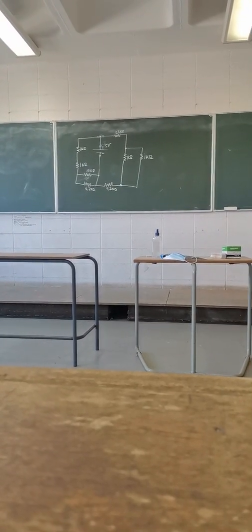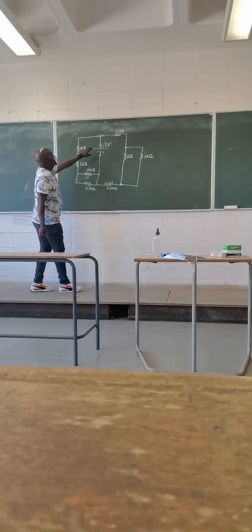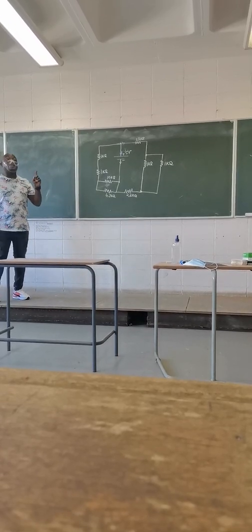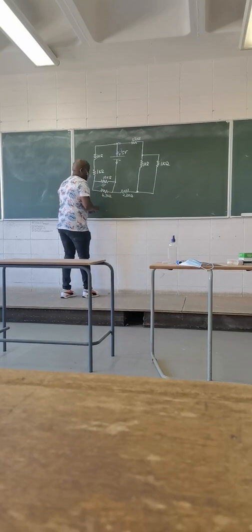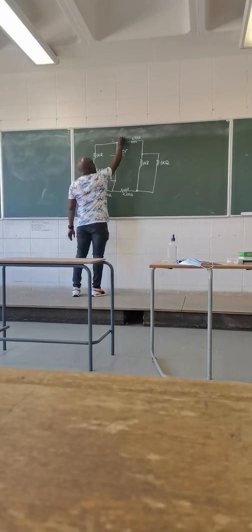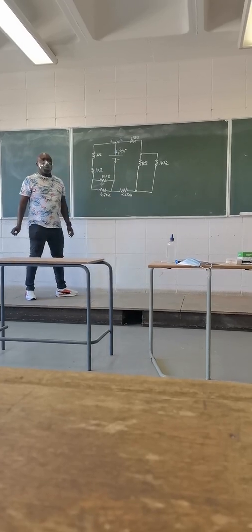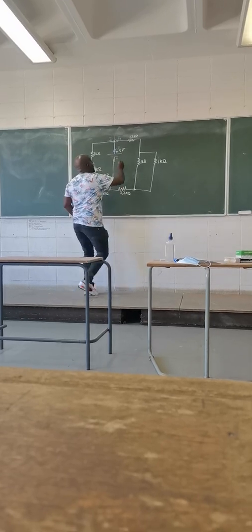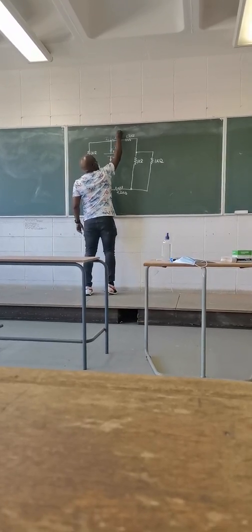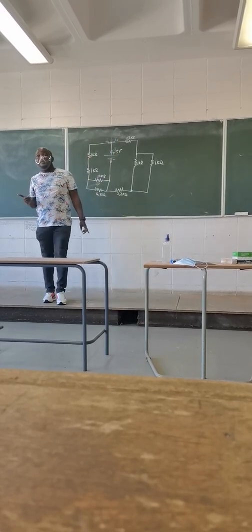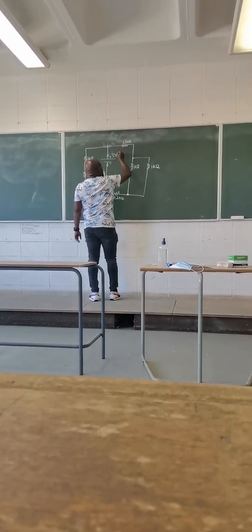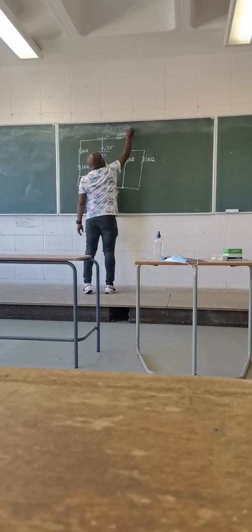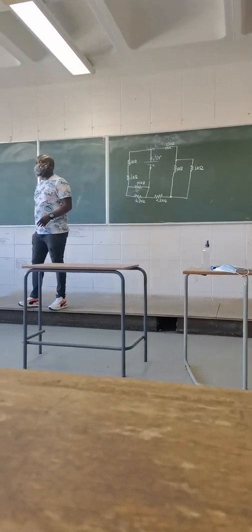You understand each other? Which means here, we can see that the sum is leaving. Let's say this one is my I1, that one is my I2. If I look at this junction, I can say it is a junction whereby the current entering the junction, which is your I total, is equal to the sum of the current leaving the junction. You understand each other? Yes.